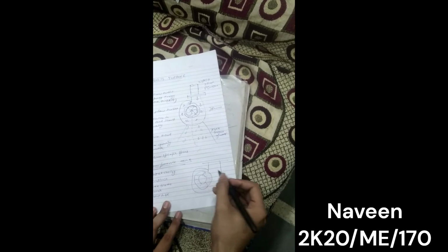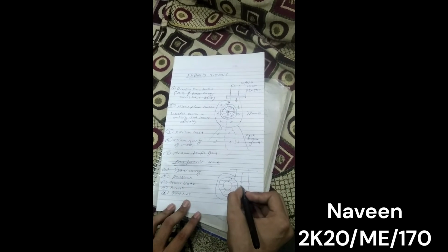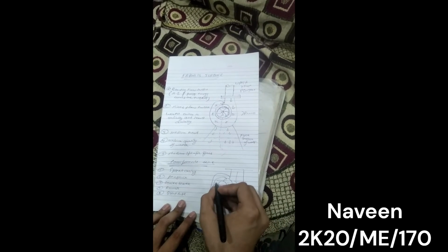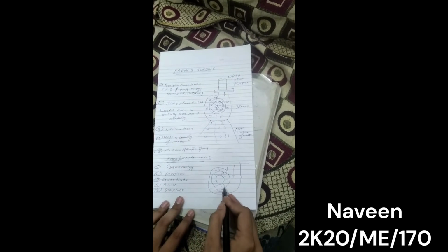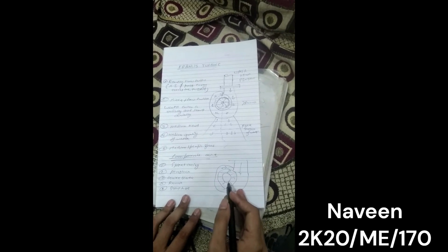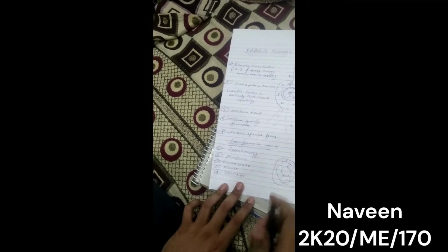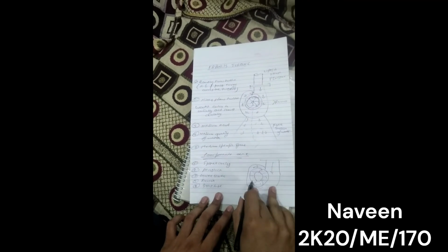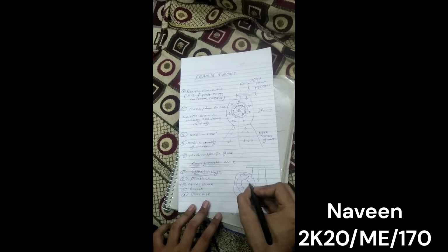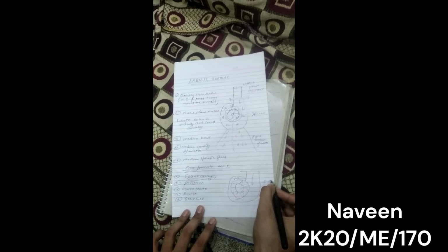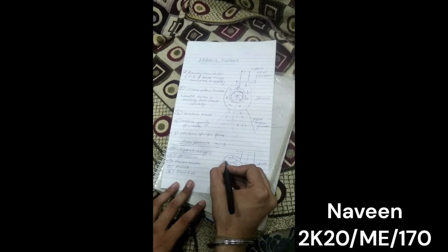So here is the spiral casing, which has maximum area at the entrance, as you can see, and nearly zero at the tip. The area of the spiral casing decreases uniformly along the circumference, and water from the penstock through the guide vanes uniformly distributes over the runner vanes. And these are the spiral casing, and these are the runner vanes, and these are the guide blades.